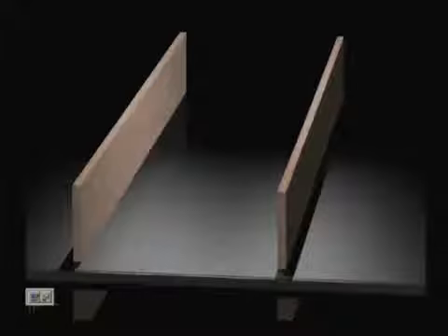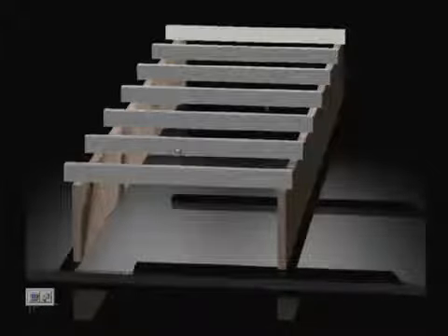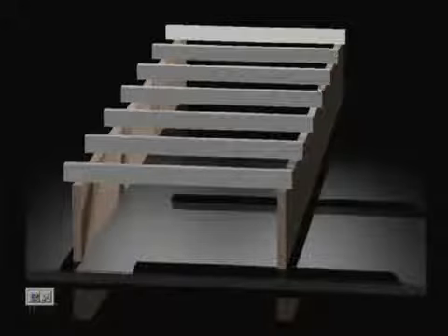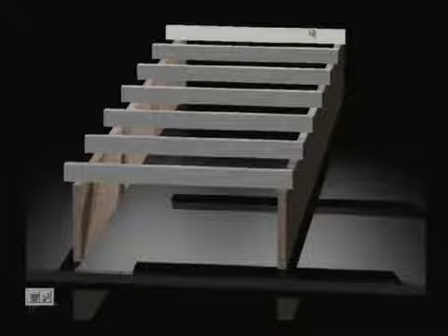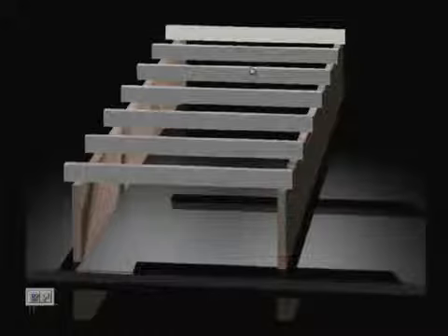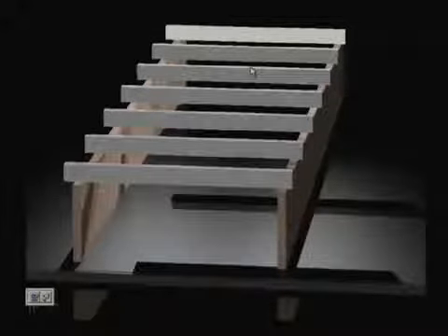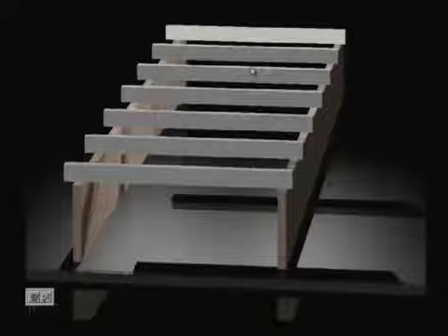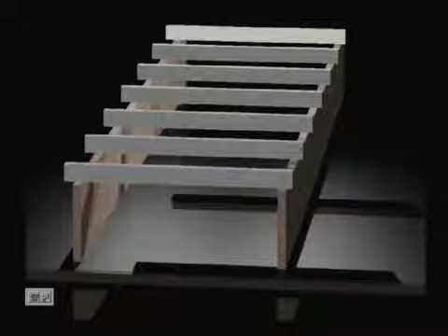Let us review it. So, we have two brick walls, which we can take as 250 millimeter width. Just for clarification we have drawn it like this: there are so many beams at 3 meter spacing covered by the roof or slab. These are the different beams, but we have constructed these beams integrally with the slab. So, we can take the action of T beam.